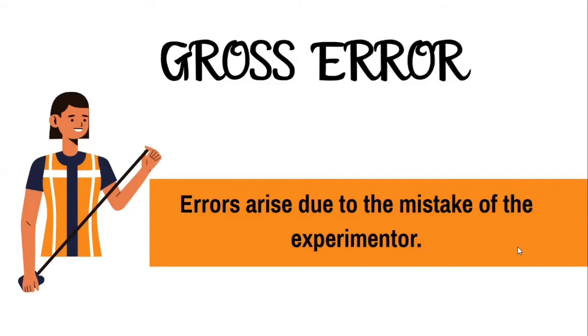You have not connected the diode in proper polarity, or the terminal is not connected properly. Or there are cases where you will not connect the ground and power supply properly. There are also cases where the ground and power supply wires, the metal contact, is not proper. All those mistakes are caused by the experimenter himself. Those experimental errors are called gross error, something that we do.